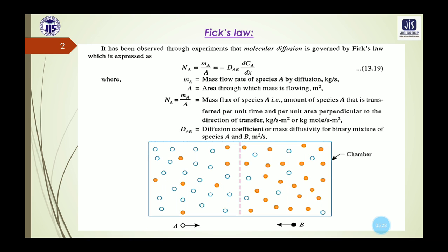So this is the concept of diffusion mass transfer, and the difference between molecular diffusion and eddy diffusion we have discussed just now. We have seen that in case of eddy diffusion, as the diffusing fluid is in turbulent motion, the mass transfer is much more rapid compared to molecular diffusion.